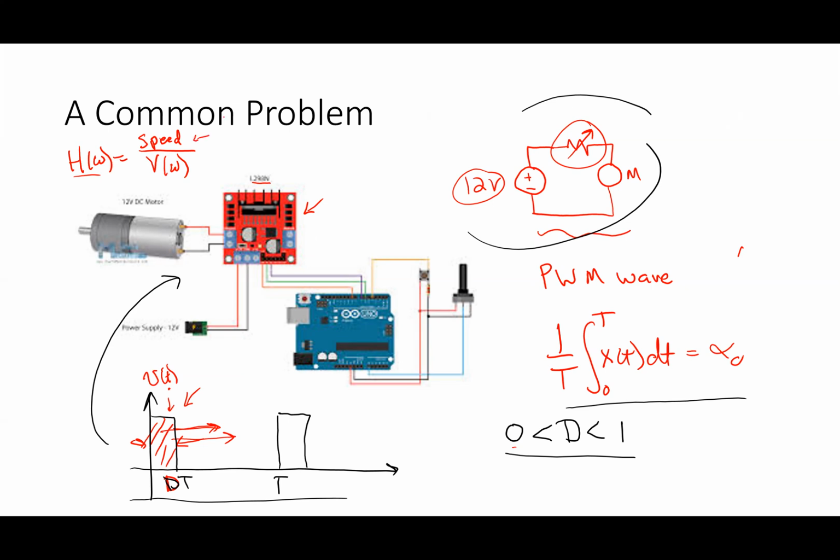All right, this idea is called filtering. When I'm using the transfer function like this, I'm usually designing what I call a quote filter, which basically takes sinusoids at certain frequencies and changes their amplitude and phase. Maybe it makes them go away. If it makes those sinusoids disappear, then I've filtered them out. It might make them get bigger. All right, but this is an idea we're going to explore here in the last part of the semester, and you're going to play with it a little bit in the project.